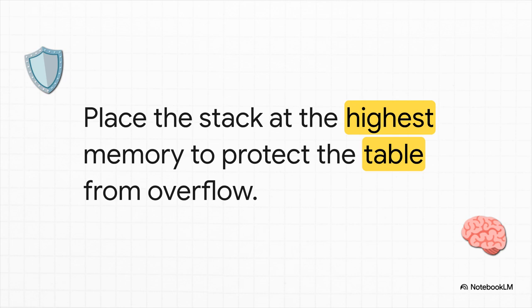So, a clever embedded design places the interrupt stack high up at the very top of the memory layout. This ensures that if a runaway stack overflow occurs, it just descends into empty free space. This gives your system a fighting chance to throw an error instead of just immediately bricking the device.